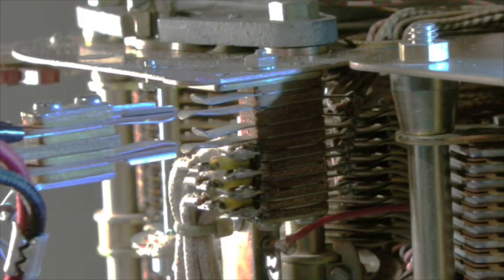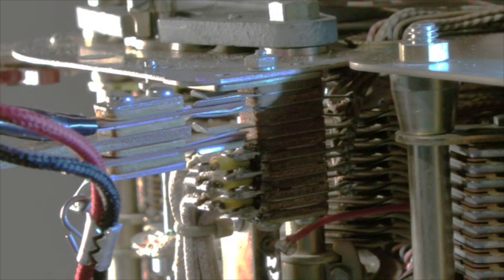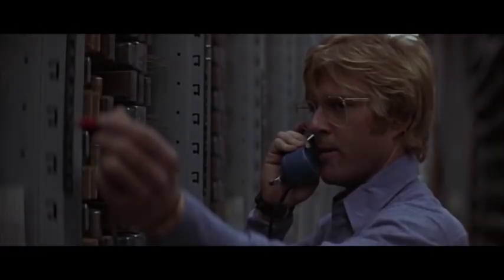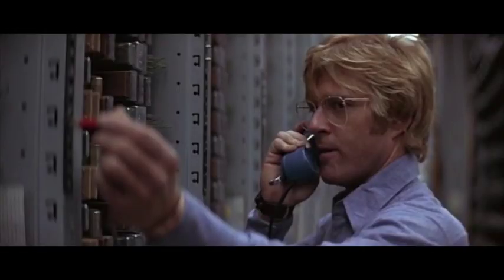As you can see here, with the test set plugged into an idle line finder, the technician can test for dial tone or dial a call through the switch train. If a switch is in use, the tech can test for a conversation, for an off-hook telephone, or for a trouble condition. And here is a well-known CO technician about to perform a test using a Western Electric 1013A dial hand test set.